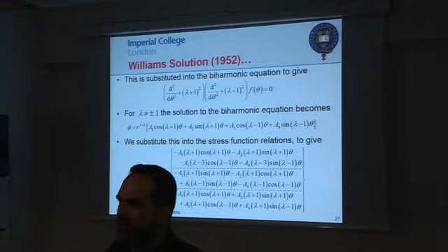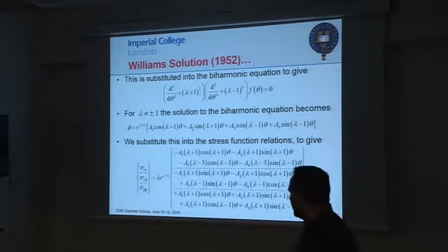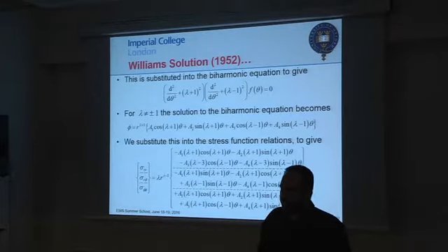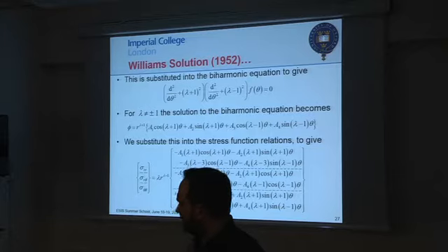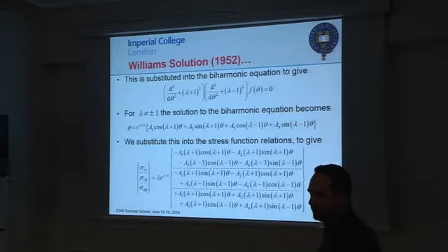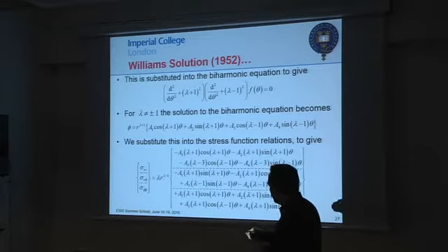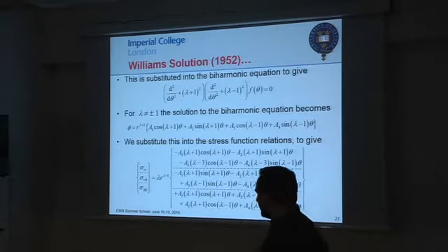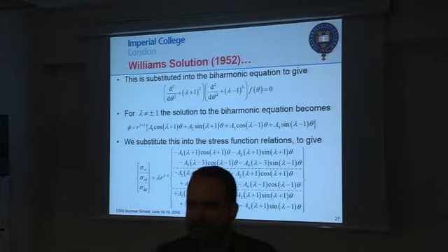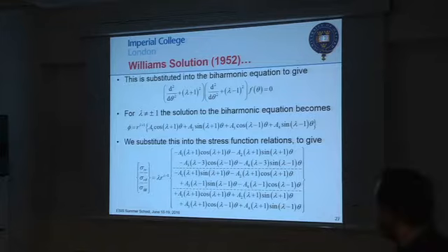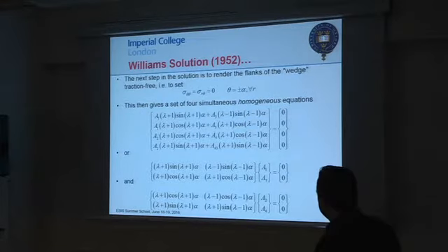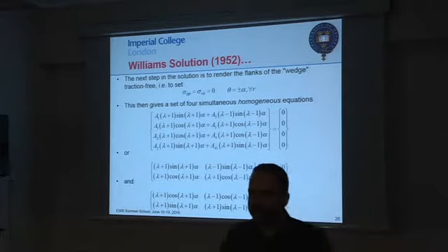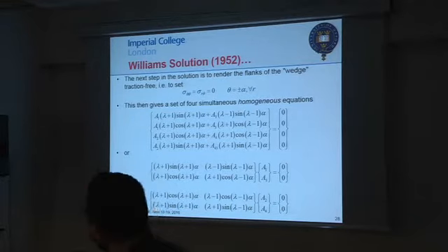I'm not going to go into the maths very much, but I just want to show you where it comes from. That means that if you substitute in the equation of stresses and you compute the derivatives, the three stress components in 2D come out to be lambda multiplied by r to the lambda minus 1 multiplied by these three functions that identify sigma rr, sigma r theta, and sigma theta theta, which are the three components of stress in the polar axes. Now, this is what we have, and then you need to do a few manipulations. So the first thing you need to do is apply the boundary condition to find some of these constants. And what do we know?